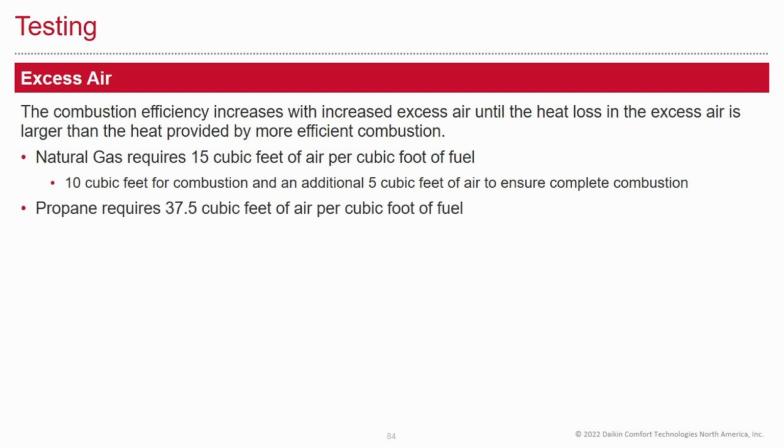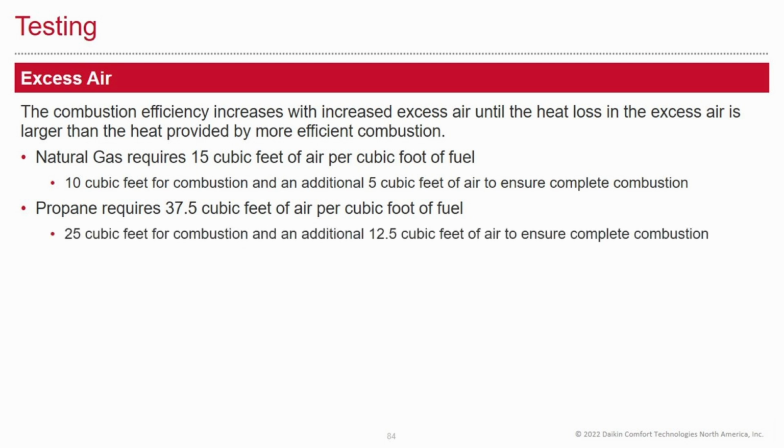Propane requires 37.5 cubic feet of air per cubic foot of fuel, 25 cubic feet for combustion, and an additional 12.5 cubic feet of air to ensure complete combustion.